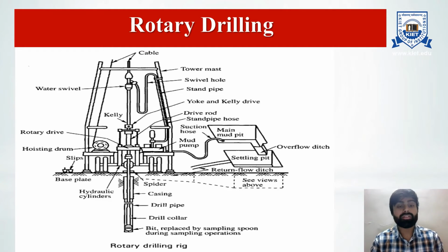Rotary drilling is used for making holes in soft rocks. As the drilling rod is rotated, the cutting bit shears off chips of the material penetrated. A drilling fluid under pressure is introduced through the drilling rod to the bottom of the hole. The fluid carries the cuttings.